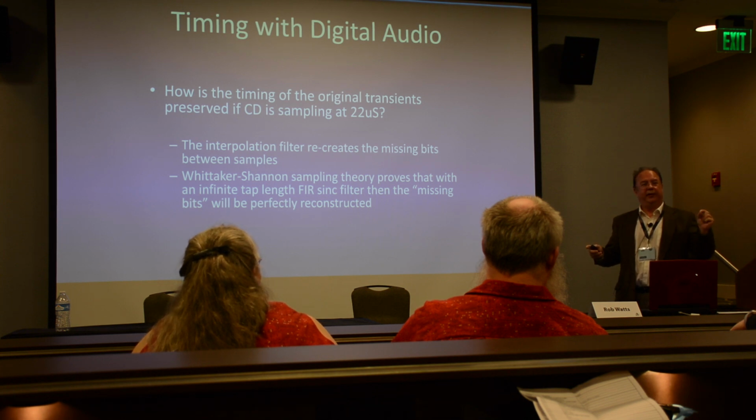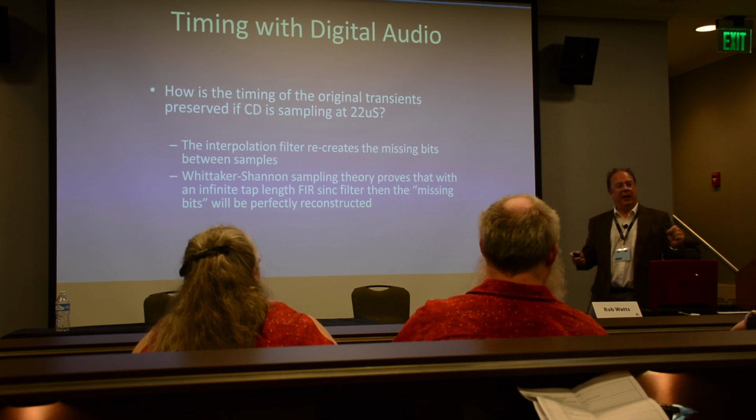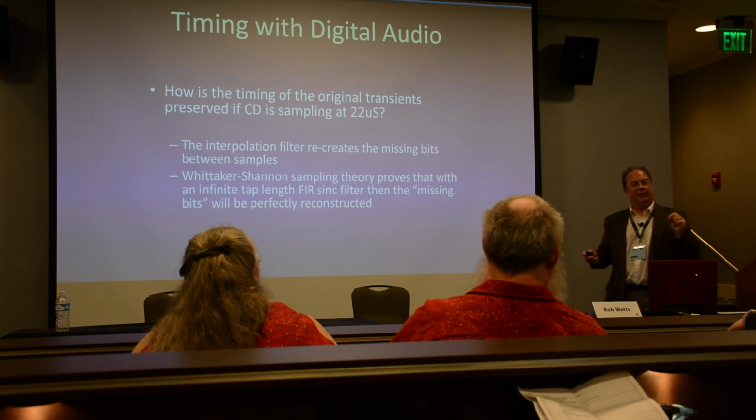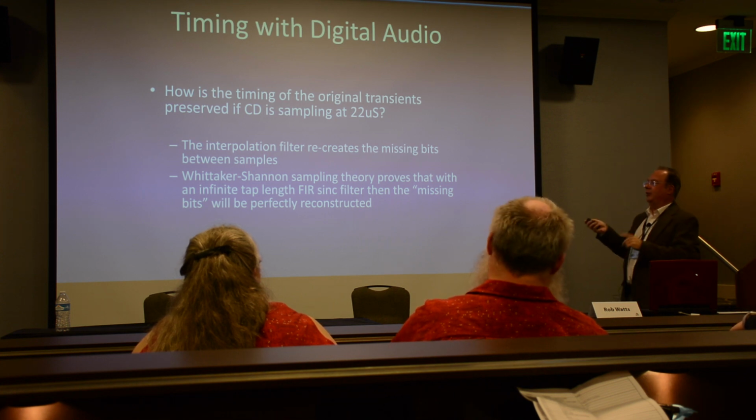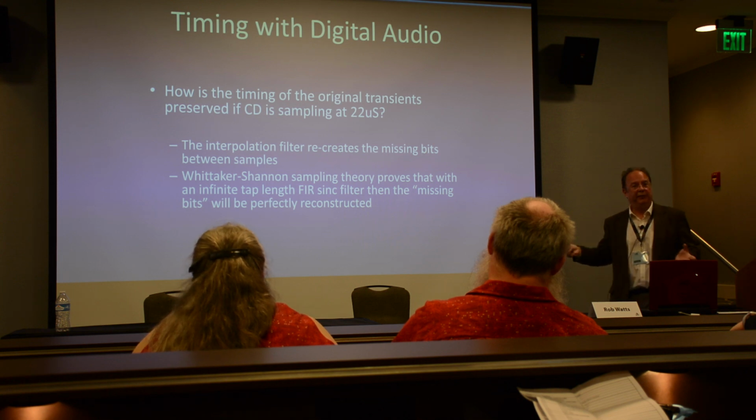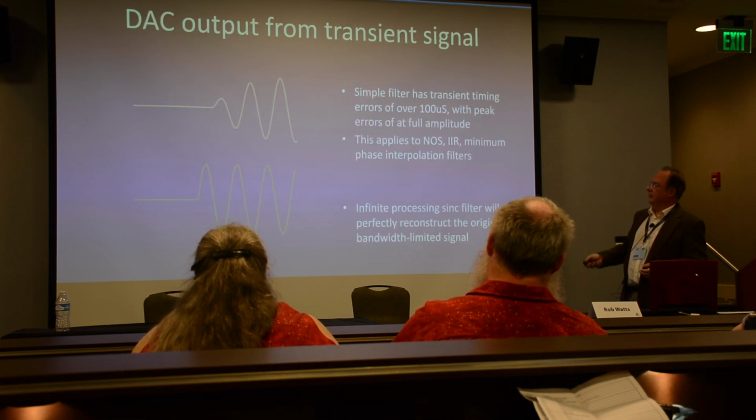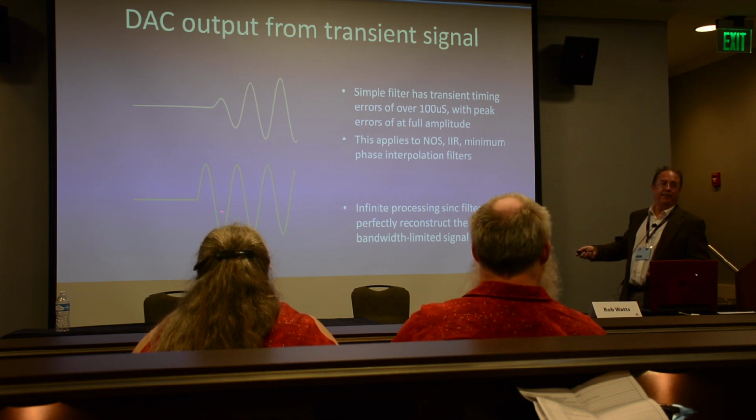There's only one requirement that you need for this. The signal must be bandwidth limited. So long as it's bandwidth limited and you have a Whittaker-Shannon sinc function filter, it will perfectly reconstruct it. So you will get this missing pulse back.